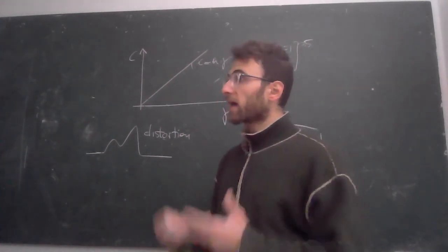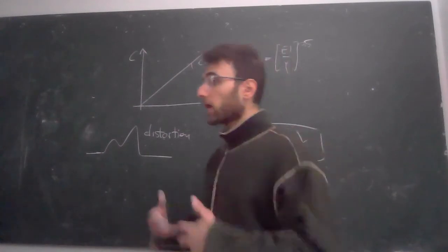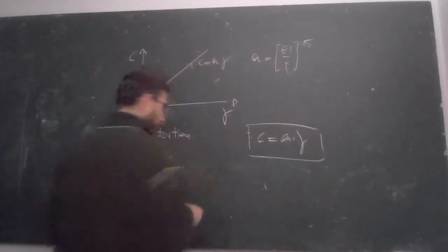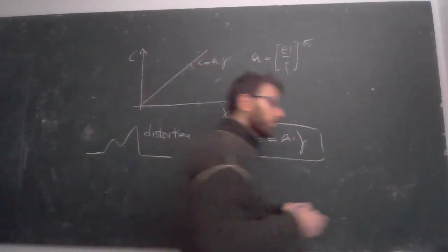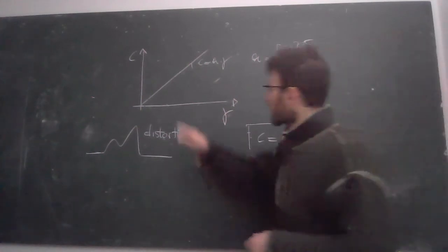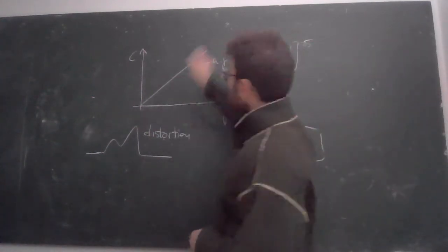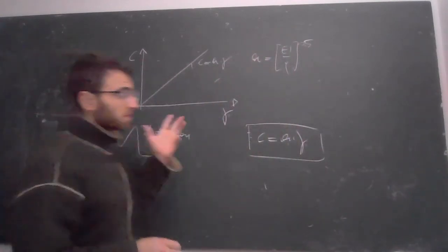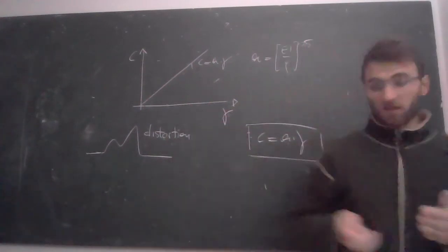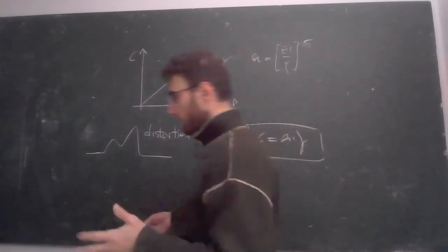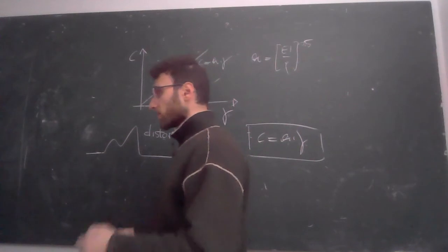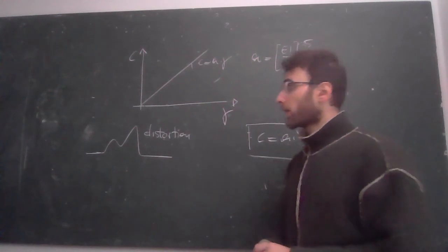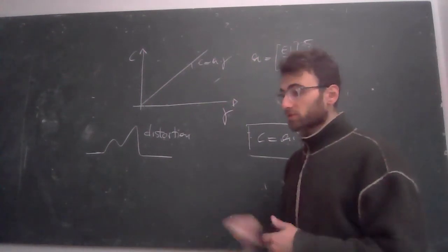The beam is the mechanical example of a highly dispersive medium. But do waves in a beam actually behave like this? This is actually the dispersion curve of a beam. Well, this is an Euler-Bernoulli beam, so we have many assumptions. Namely, as I said, the cross-section remains plane and orthogonal to the neutral axis of the beam. Then we are neglecting the contribution of shear.